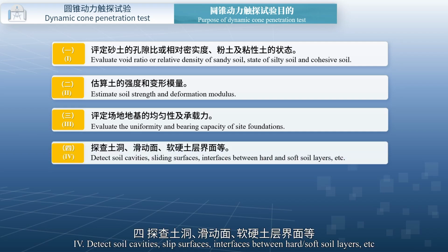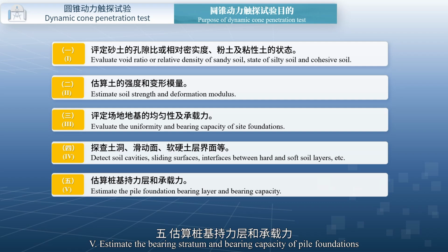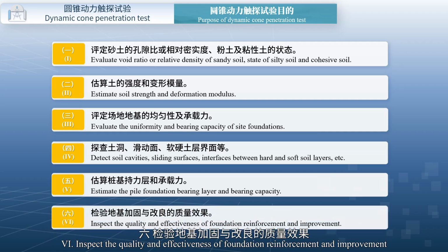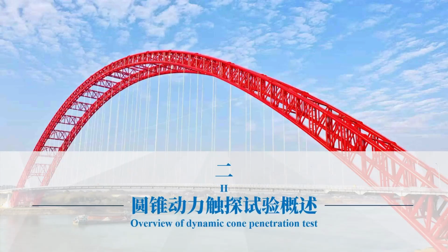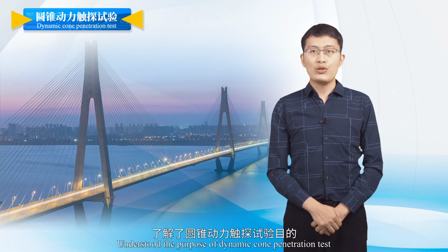Fourth, detect soil cavities, slip surfaces, interfaces between hard or soft soil layers, etc. Fifth, estimate the bearing stratum and bearing capacity of pile foundations. Sixth, inspect the quality and effectiveness of foundation reinforcement and improvement. We have now understood the purpose of dynamic cone penetration test.